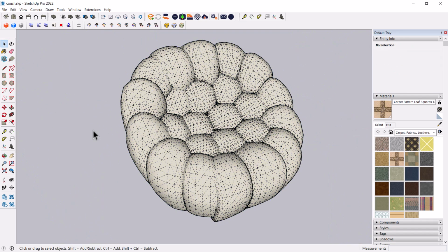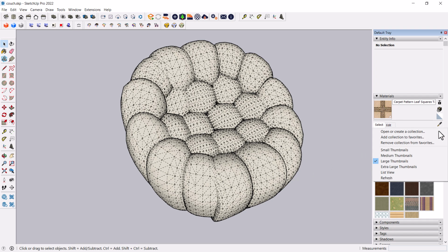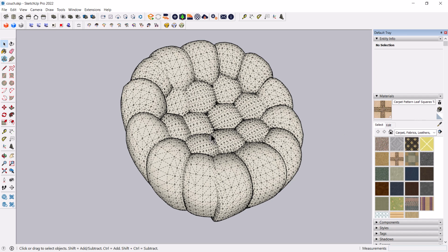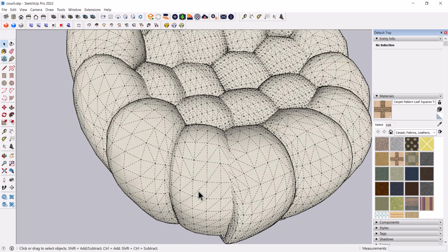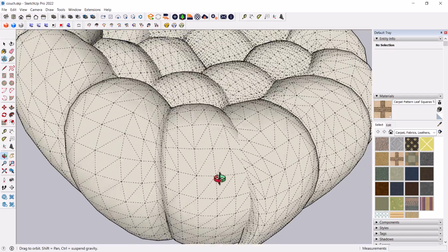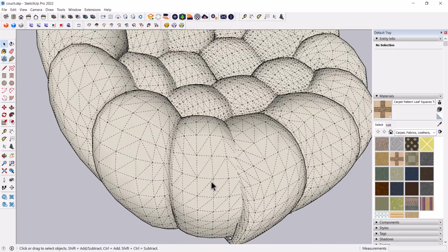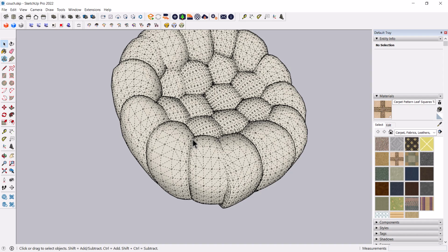For example, if you want to paint this a material in Revit, you have to delete all materials here in SketchUp. You can literally just come and in your model delete all of the textures that are in the model. If there are different materials, you'll have to create a tag in SketchUp for each unique material. But then the worst problem is, because SketchUp models have these facets to them, they are triangulated. Nothing is really bulbous. It's actually just lots of little flat pieces. You could run into problems.